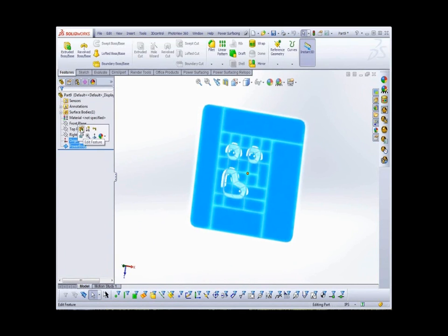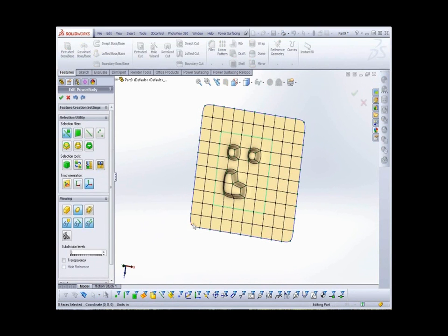And in case you want the corners to remain sharp, you can always head back into edit mode and give the corner vertices a weight of 100% with hard edge.